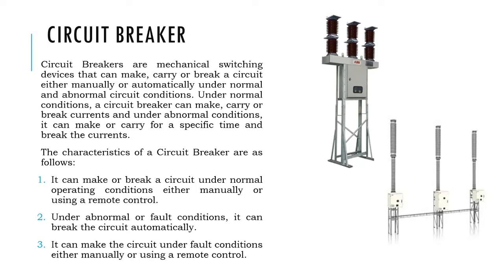It depends upon the voltage level. At low voltage systems, generally air circuit breakers, ACBs, you can see for 415 volt systems. And if we go to the 11 kV, 33 kV level, up to 33 kV, you can find vacuum circuit breakers. In some 33 kV projects, they are using SF6, but mostly 33 kV is vacuum circuit breakers.